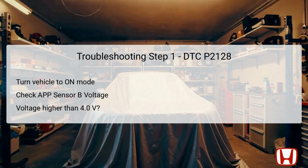If the voltage exceeds 4.0 volts, this indicates a duplication of the failure, confirming that there's an issue that requires further investigation. The analysis at this stage serves to validate the existence of the problem before proceeding to inspect the sensor itself. Recognizing this high voltage condition early on is critical, as it directs technicians towards potential faults either in the sensor or its respective circuits.